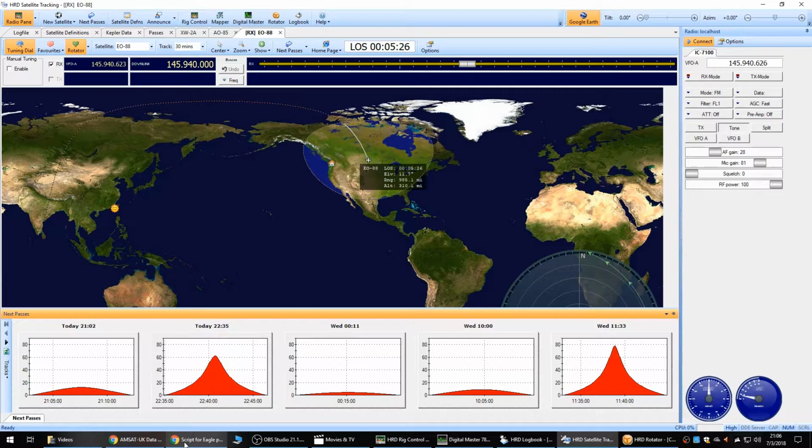Now that all the basics are set up, let's check what satellites are about to pass overhead and figure out which one we should connect to. See how the screen shows the pass that will be occurring and how we have degrees of this pass? We need to keep this above 10 to even have a chance of making a contact. Next, check the clock and see how much time you have before the contact is about to happen. For example, in this screen you'll see we have 1 hour and 34 minutes until the next contact we could possibly make. This gives us time to get a few things ready before the satellite is overhead.